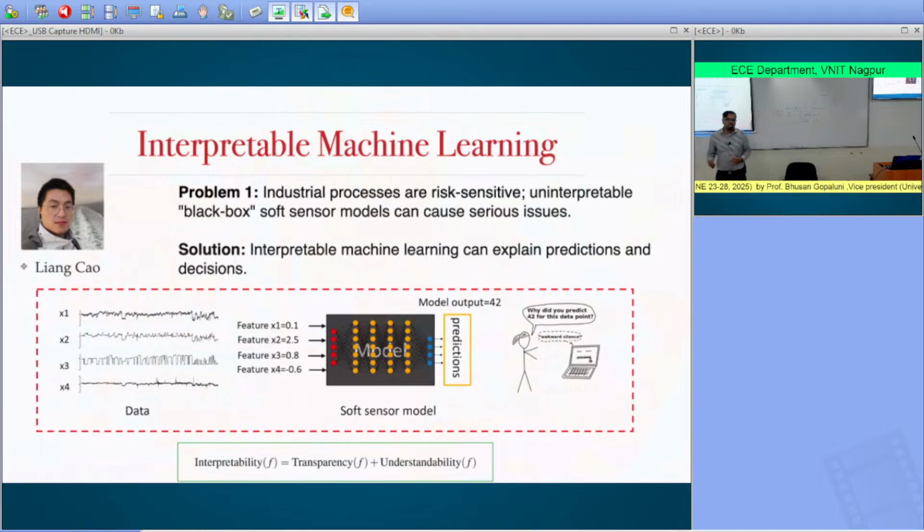So their natural reaction was, okay, I'm going to take the model predictive controller offline and drive the process myself. They were able to do that. Then they wanted to figure out why the model predictive controller dropped the feed rate. After some further analysis, their engineers found that a few days prior, they were doing some repairs on a certain line, and somebody put a clamp on a variable.